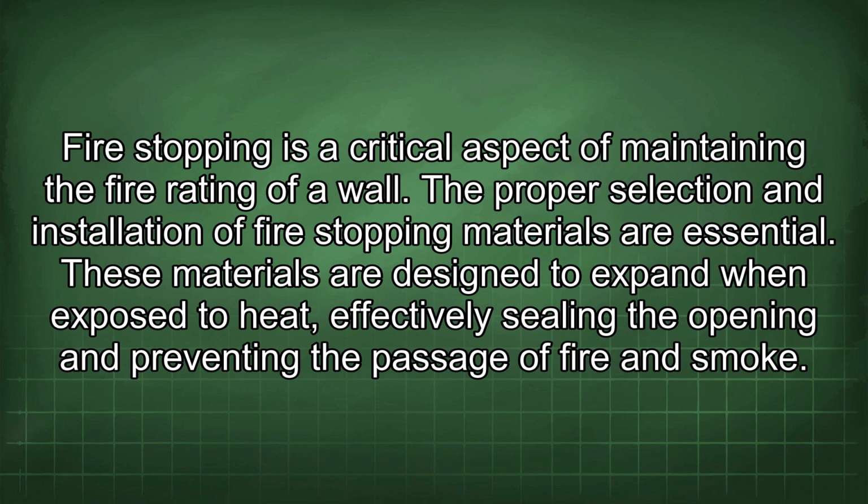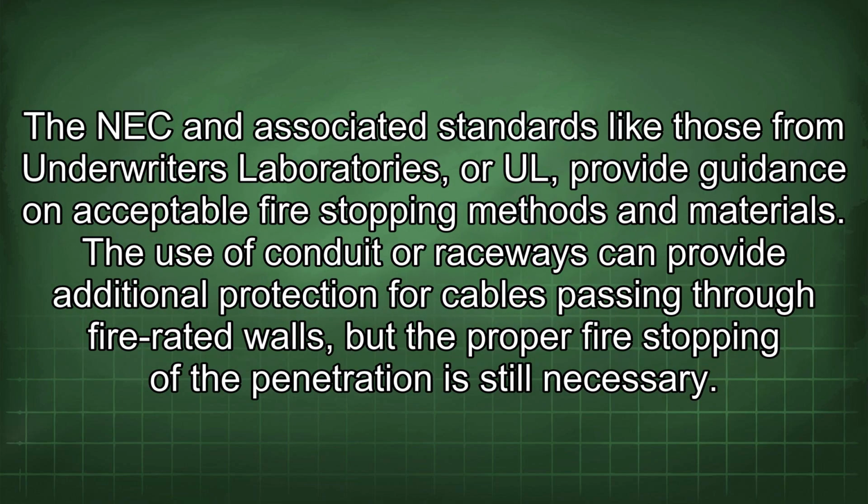These materials are designed to expand when exposed to heat, effectively sealing the opening and preventing the passage of fire and smoke. The NEC and associated standards like those from Underwriters Laboratories, or UL, provide guidance on acceptable fire-stopping methods and materials. The use of conduit or raceways can provide additional protection for cables passing through fire-rated walls, but the proper fire stopping of the penetration is still necessary.